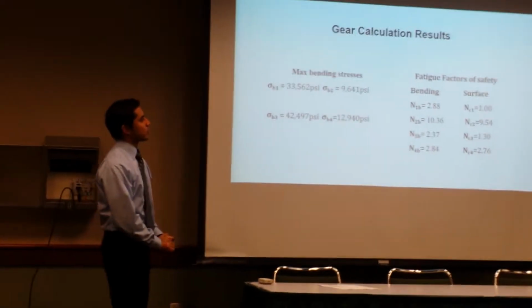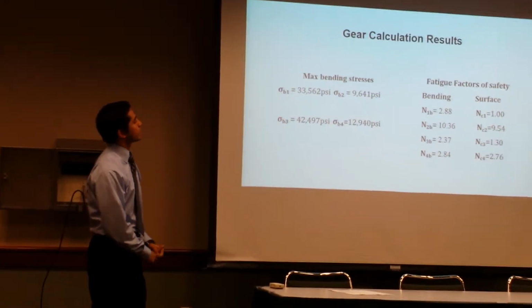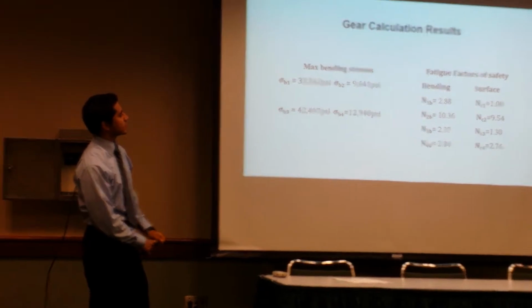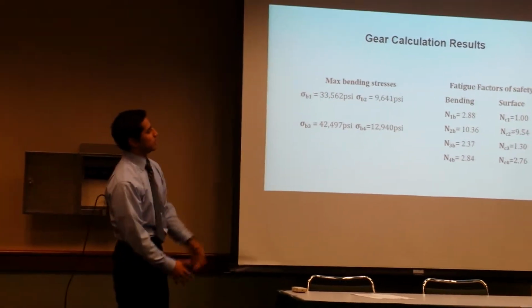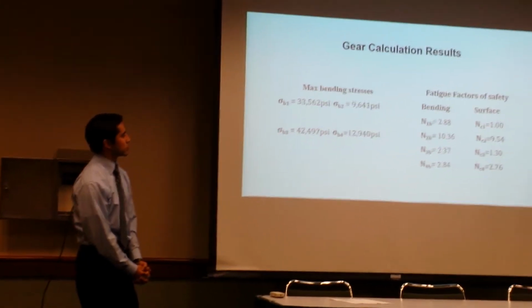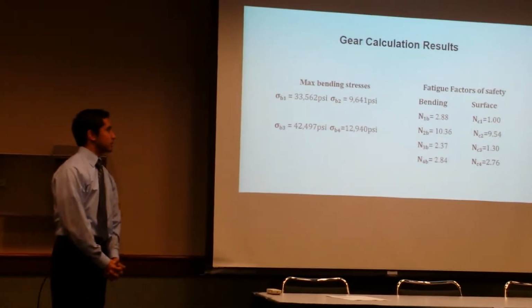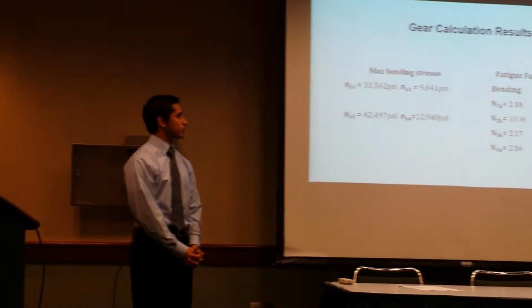Our factors of safety were all well above 1, and max bending stresses never exceeded the yield strength of our gears, showing us that the gears that we chose were actually going to last for the year that we want them to last for.